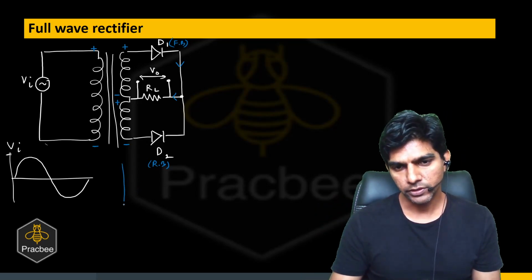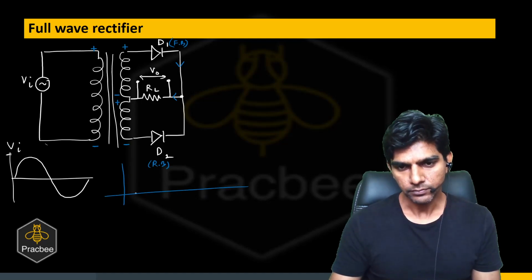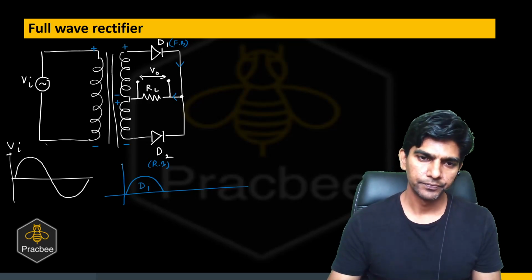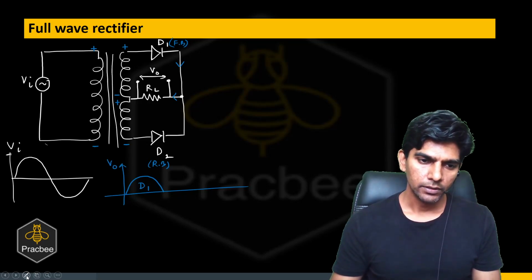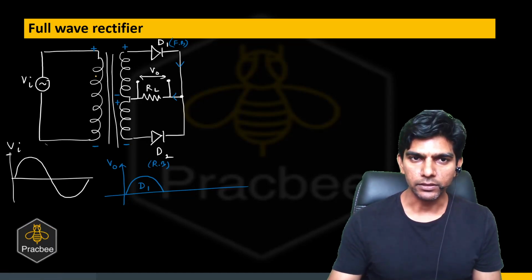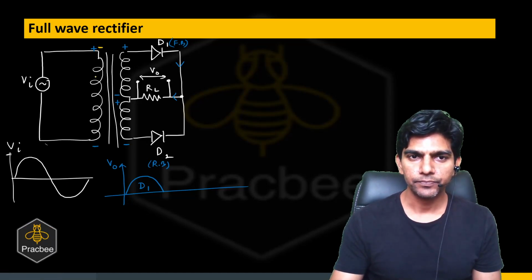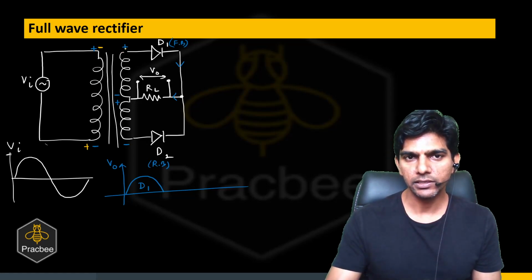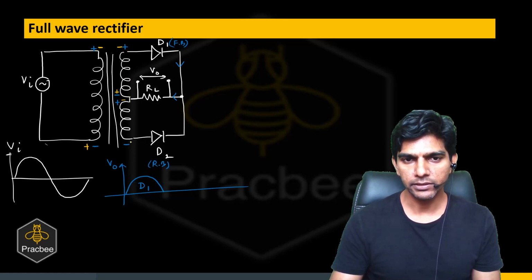If I show it on the graph, we are able to rectify a half wave, and this is because of the diode D1. This is the output voltage. Now, if we talk about the second half cycle, the top end of the primary will be at low potential, and the bottom will be at high potential. Similarly, the polarity will also reverse on the secondary side. So the top will be at low potential, then plus, and then minus, and then plus.